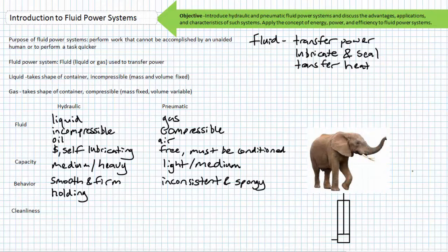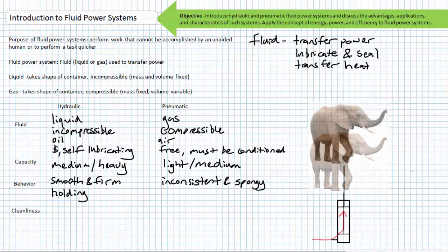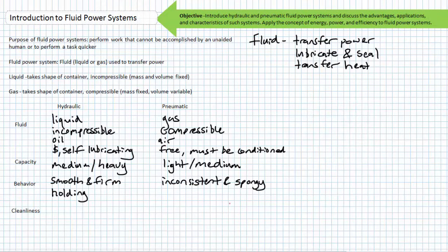Want to lift a heavy load and keep it lifted? Let pressurized flow enter a cylinder and lift the load. Trap the liquid and forget about it. Since the trapped liquid is incompressible, that heavy load isn't going anywhere until you lower it, hopefully in a controlled fashion, by letting fluid slowly bleed out of the cylinder. We'll discuss flow control methods that allow the controlled descent of a lifted object in later lectures.